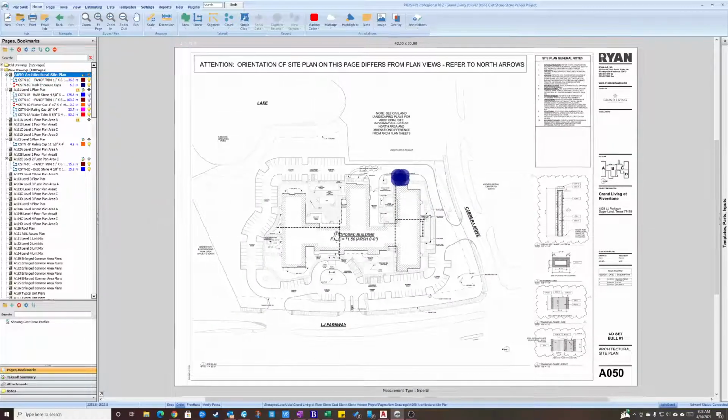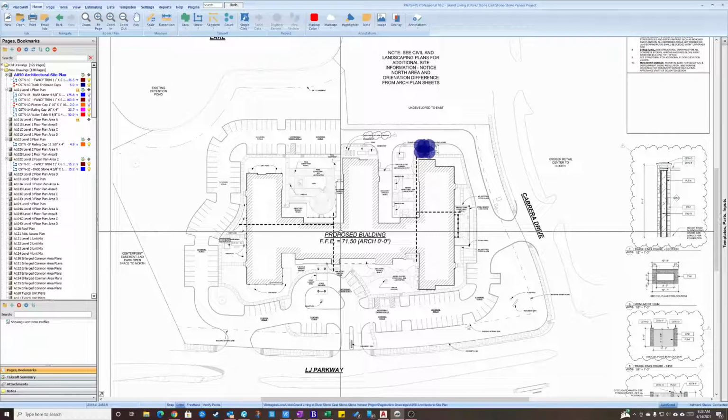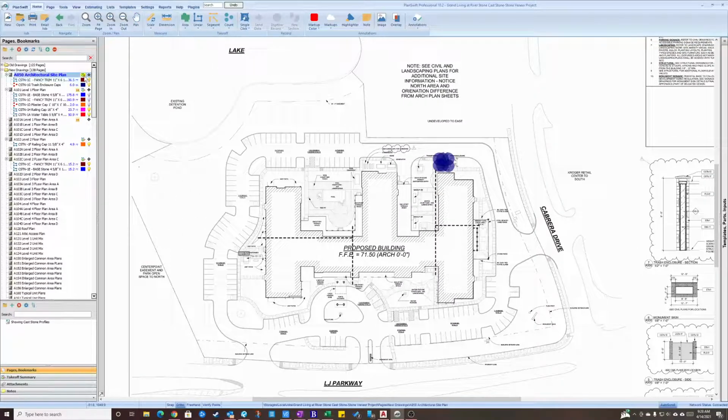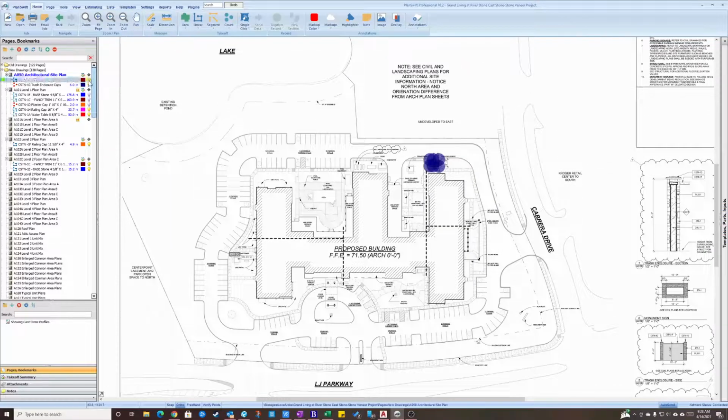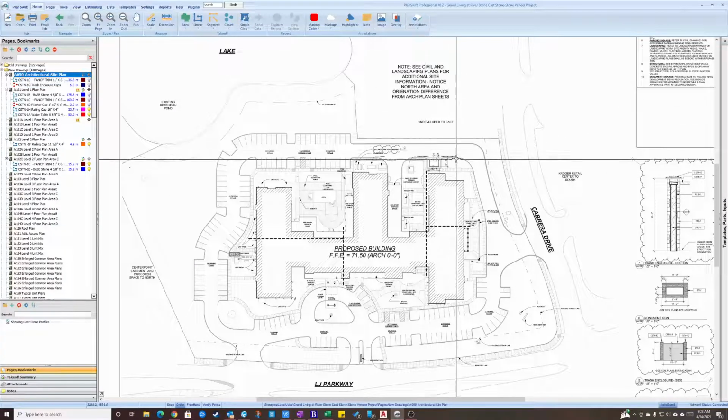Sorry about that. Essentially, let's go ahead and turn these off. You can turn markers and markups off individually, by going over here to the left hand side, selecting the page that you're on. You can just click the little light bulbs, and when they're not yellow, that's basically turning them off. You see that we turned off that stuff there.